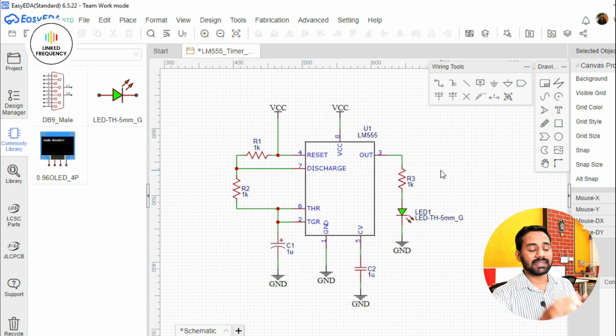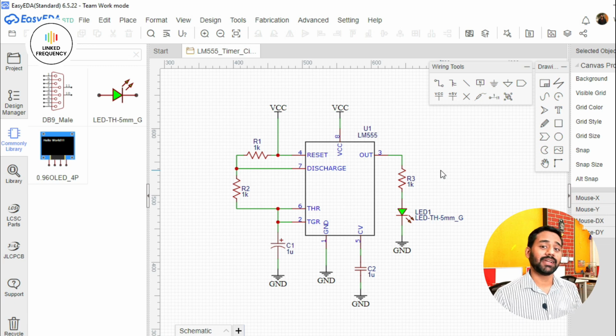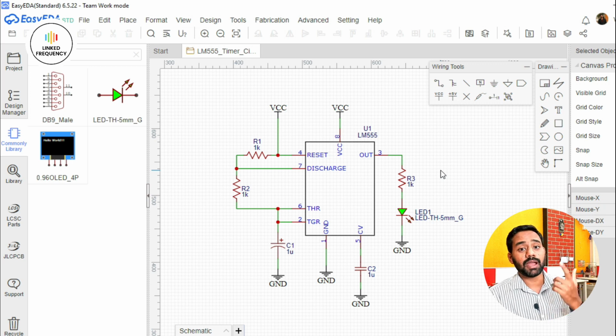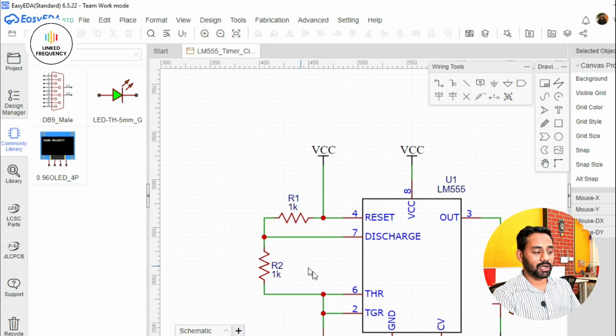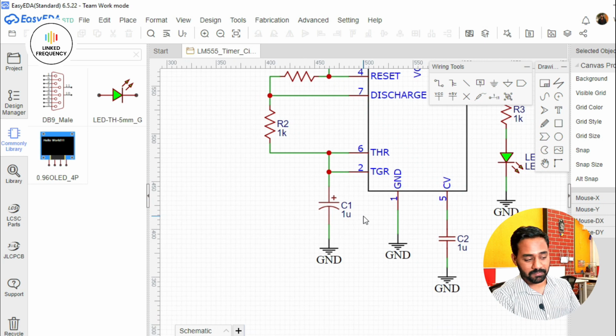This is how the entire 555 timer based Astable multivibrator will be designed. The only important thing left right now is tuning the value of resistor and capacitor, because that will decide the timing pulse width and duration. Hope you remember I mentioned the possibility of time pulse generation with respect to the 555 timer IC ranging from microsecond to an hour. That time pulse you can control by R1 resistor, R2 resistor and C1 capacitor.